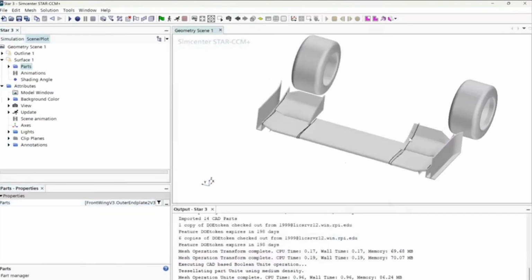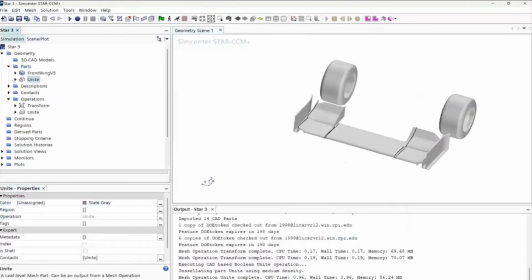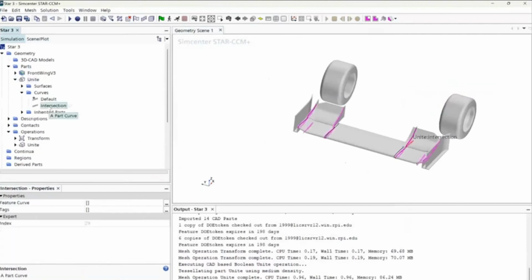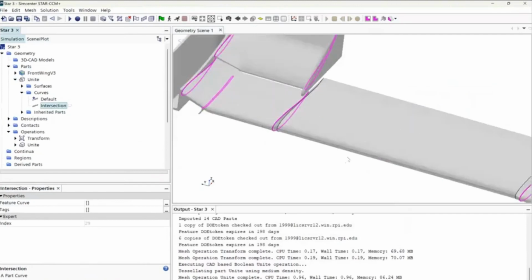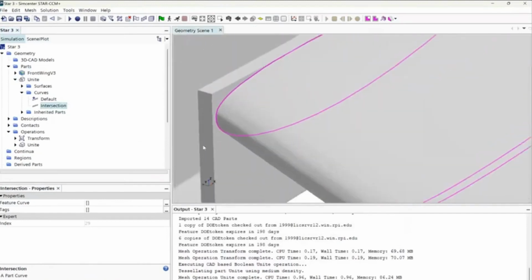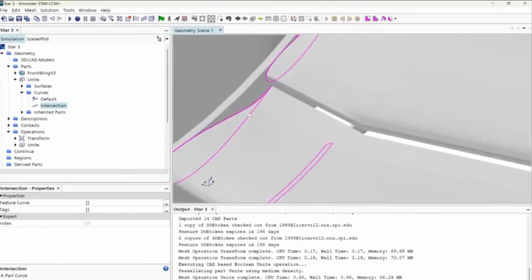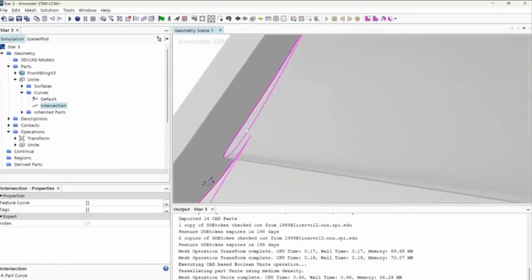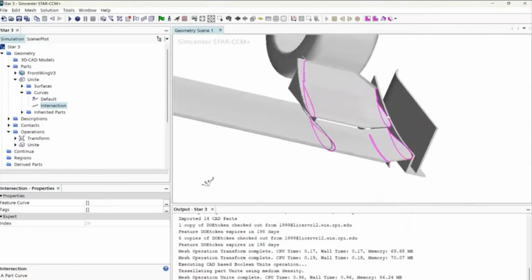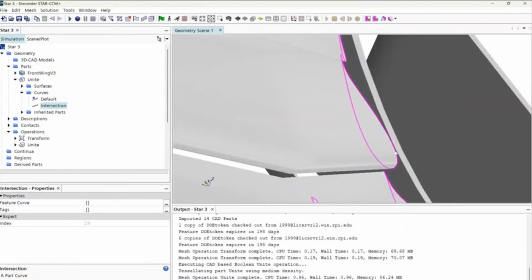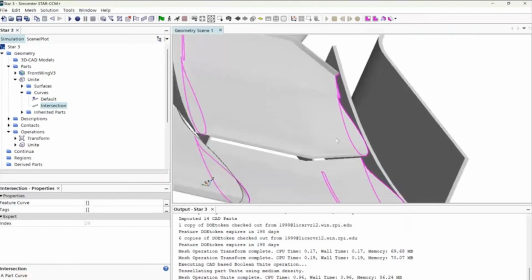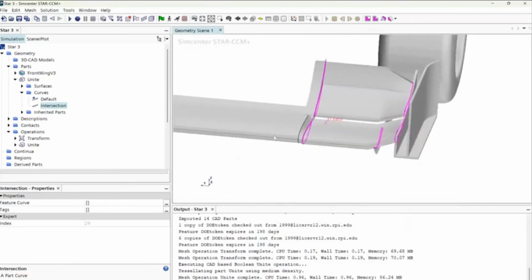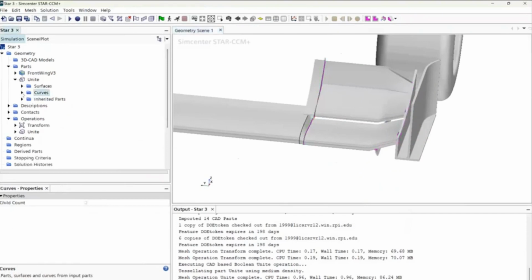Let's close this. So we have right now, we want to check, which is very important, is this. Curves intersection. Very important that we check this. Very important we have perfect intersections. Now, of course, if you see imperfect intersections, you will notice them right away. But we have perfect intersections right now. And what happened is if this was imperfect, there would be like, maybe this part would show up, but this wouldn't be here. It would be all weird and it wouldn't look like an airfoil or like the profile we've chosen.